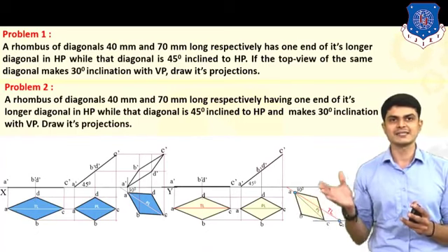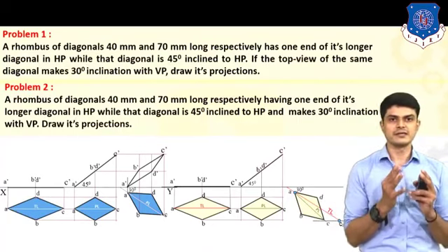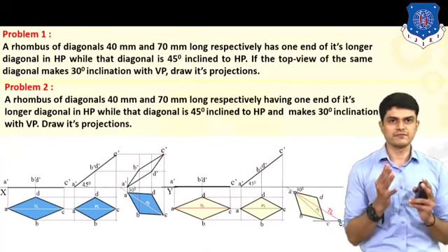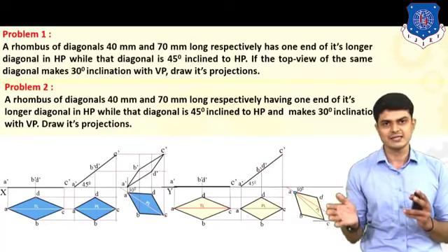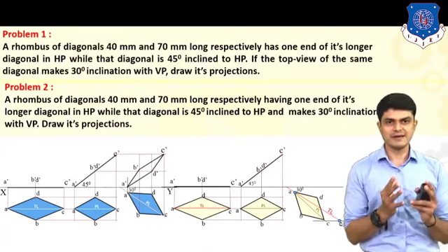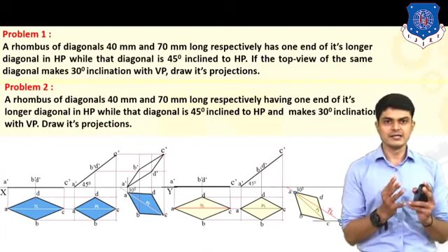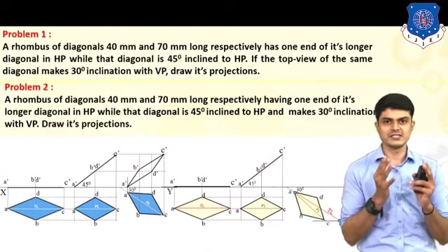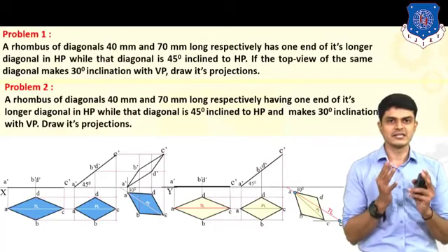And after that, you just mark these points. So this is nothing but your final object in the third step. So remember the difference here, we have taken the angle with the true length, and then after we have plotted the plan length, and based on the plan length we have drawn our object. So this method is also known as your plan length method or beta angle method. It is the most important method which is always asked in the examination. So try to get the difference between the two.